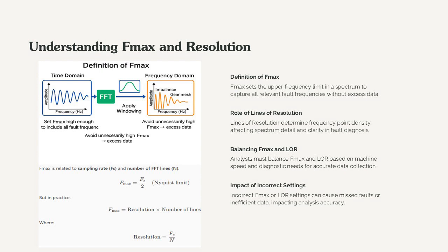Lines of resolution, LR, determine the number of discrete frequency points within the selected range, impacting the clarity and detail of the spectrum. Higher resolution provides finer detail but requires longer acquisition time and more memory. Conversely, low resolution may obscure critical fault signatures.